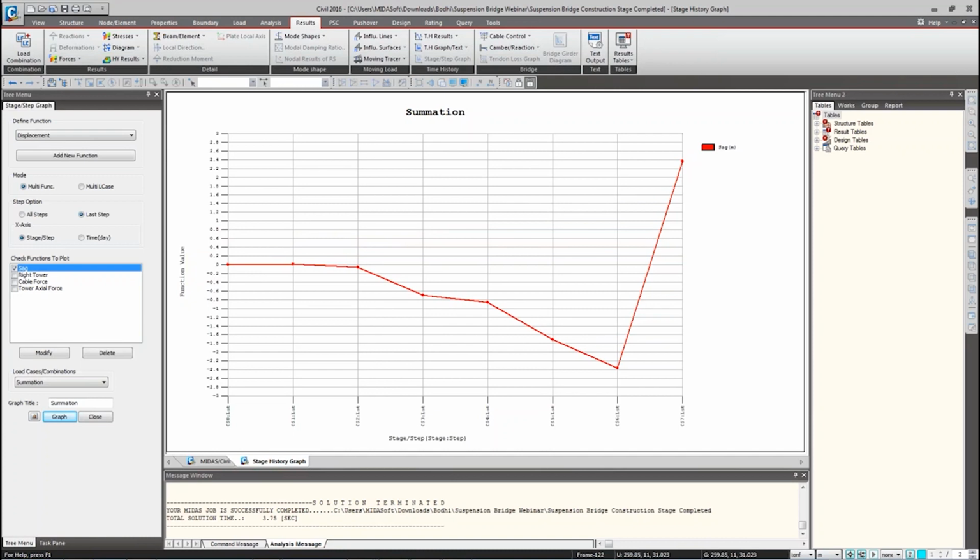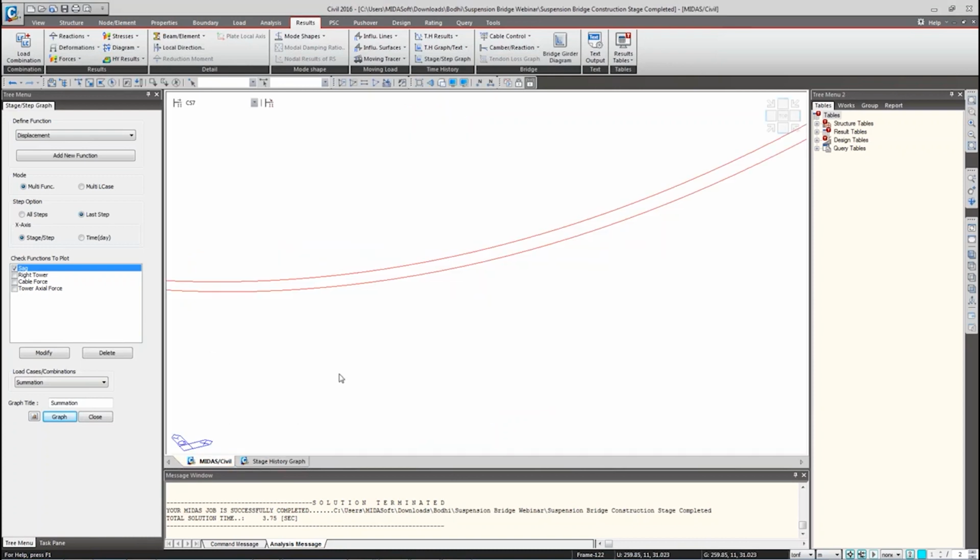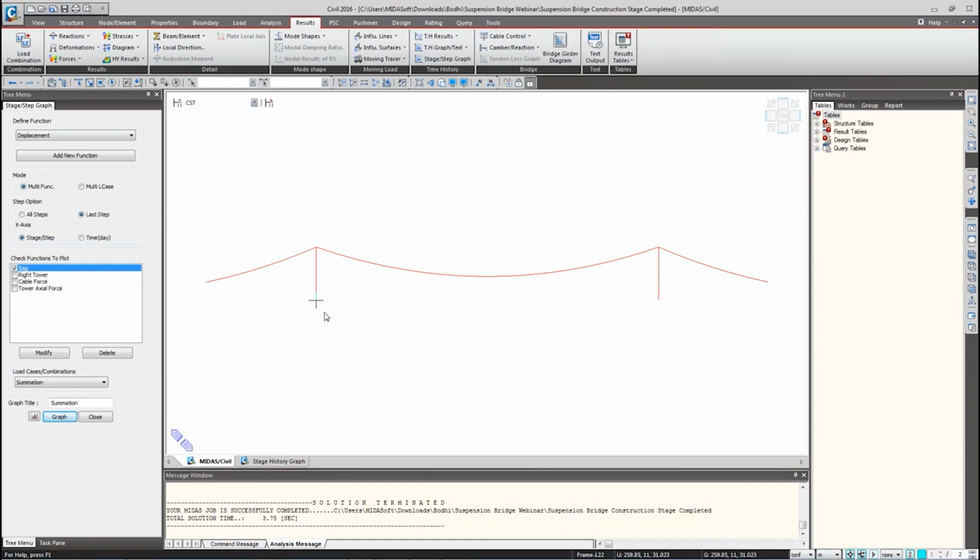other things like the setback values. Now for a construction stage, the setback value is very important, because initially in the final stage model you have a fixed sag length, that is this. So in order to have 0 moments in the pylon, what the software automatically does is that it gives a horizontal force to reduce that moment to 0. Okay, so it gives an equivalent horizontal force to reduce that moment.